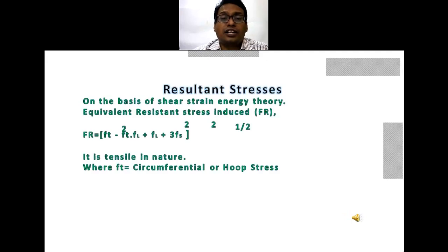Then the resultant or equivalent stress. There are different theories of failure for this calculation. Here we are considering the shear strain energy theory to calculate the equivalent resultant stress.